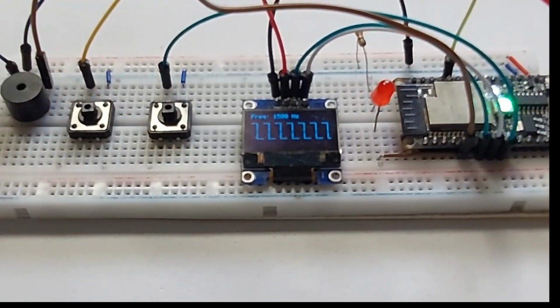And usually you have a voltage divider, and in astable mode, you have a resistor of 1K and another resistor perhaps of 10K, and you change them, and that will change the frequency, based also on the capacitors of 10 microfarad or 100 microfarad. So it's pretty similar.